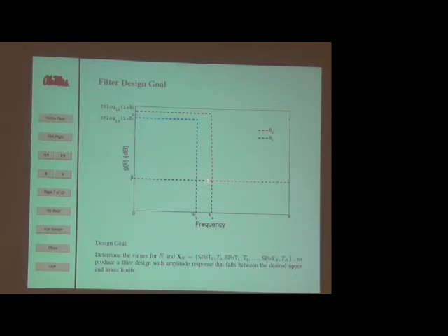And I'd like this thing to be below some value past the stop band. And my design goal, well, I need to find the number of sine power of 2 terms required to implement this filter, and I need to determine their values and which filter tap they go with. So these, if you will, are the parameters I'd like to determine.